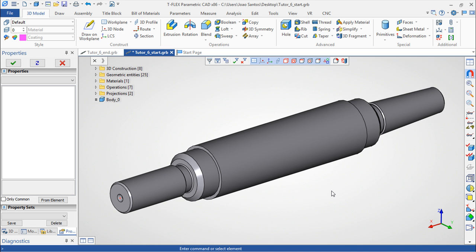If the workpiece experienced damage for that given static load, then it does not make sense to carry out the fatigue analysis, because we need to change the structure of the part in such a way that it is steady with the loads that are applied.